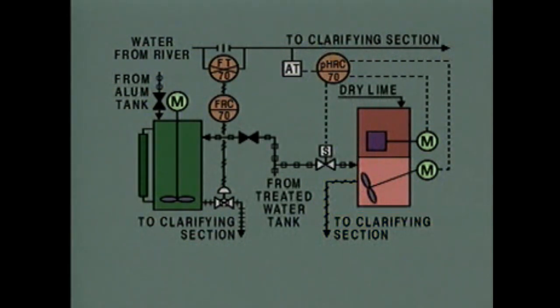The lime solution carried by the hose is made in the mix tank of the lime system, so the tank and its motor-driven mixer could be checked for visible problems. Lime is added to the mix tank by this motor-driven shaker, so the shaker could be checked to see if it's clogged or damaged. The motor could also be checked for problems. Lime for the shaker comes from a hopper that's filled manually, so another thing to check is whether the hopper contains a supply of lime.